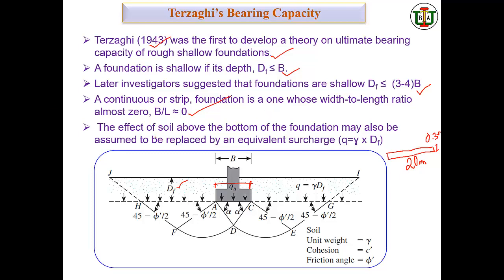The effect of soil above the bottom of the foundation may also be assumed to be replaced by an equivalent surcharge. Suppose you can see this is the bottom of the foundation, right? Above this you have some soil here, on this side and the right side also. This soil also gives some force to the foundation because it has self weight and other pressures also. So this kind of load we call surcharge.